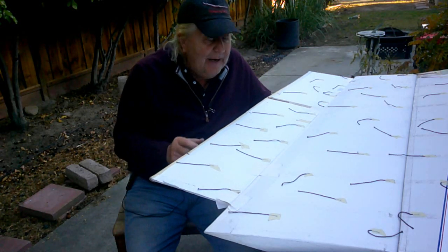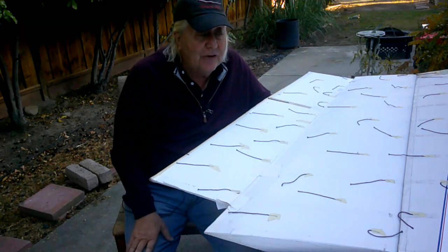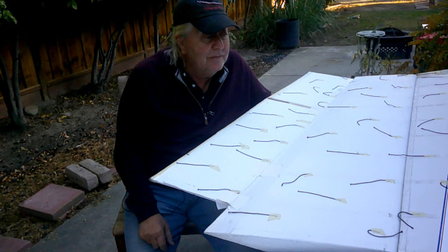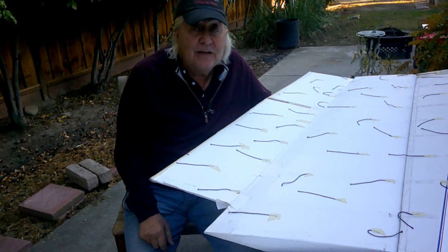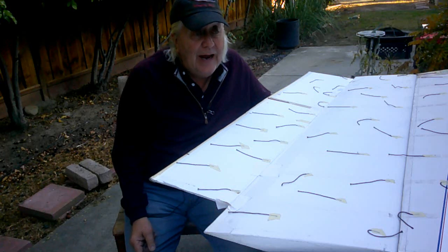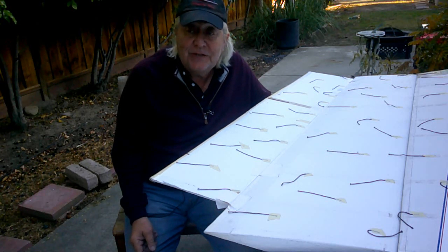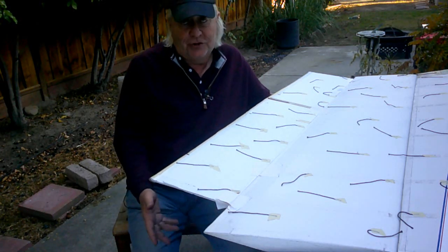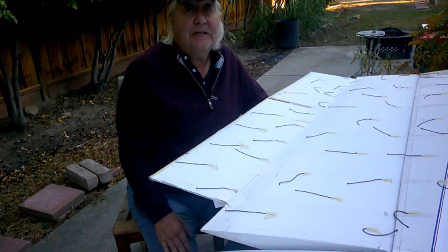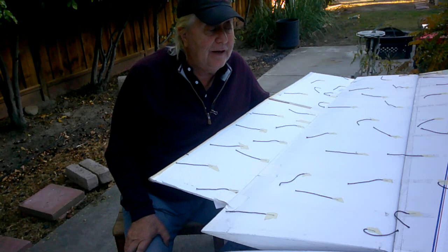And if I added 9 inches to the entire chord, well, now I'm up around 165 square feet of wing. And that's starting to get a little bit large if you want to go fast. The more wing area you have, the more energy it takes to go fly fast. It'll fly slow, much better, but you want to go fast. You want the least amount of wing area possible and go like hell.